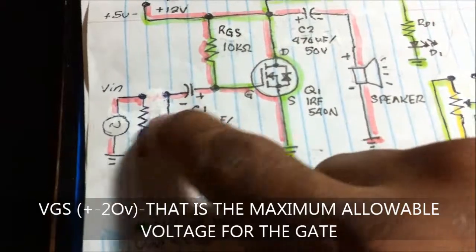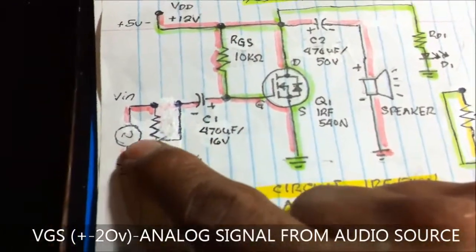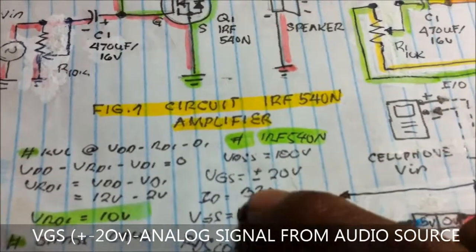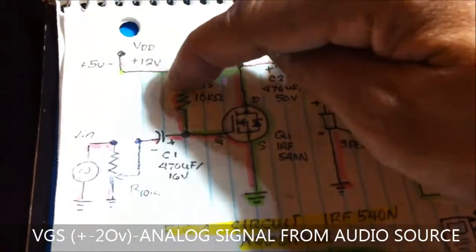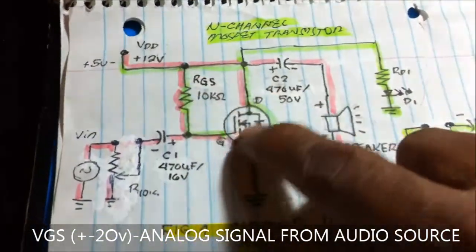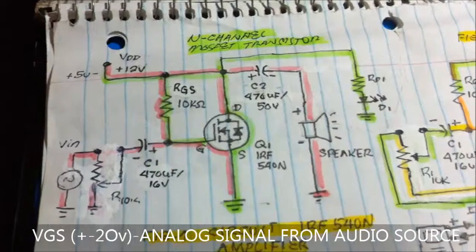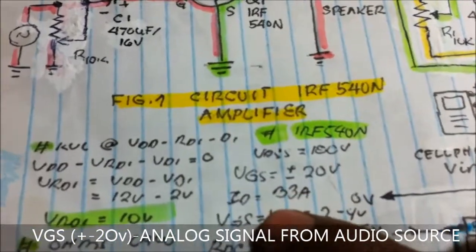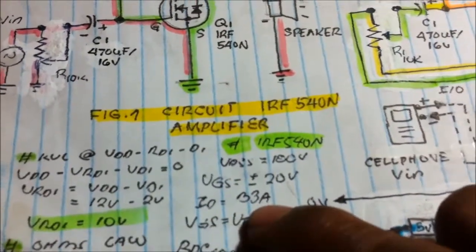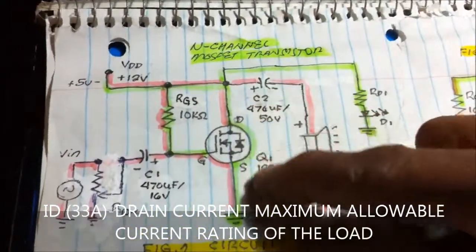Because this is, did you see this line? This is an analog signal, negative, positive. It refers to this voltage source. This one, gate to source, positive, negative, 20 volts, VGS. Also referring to this for DC biasing. Should be 20 volts. If you apply more than 20 volts, the Mosfet will blow away. It will burn. And the drain current is 33 ampere according to the datasheet. So the 33 ampere is used.